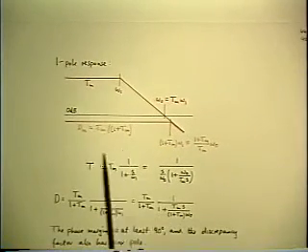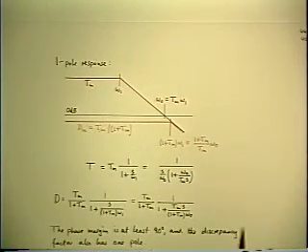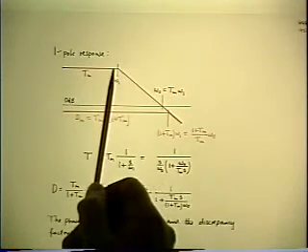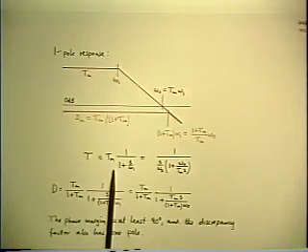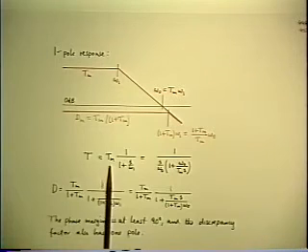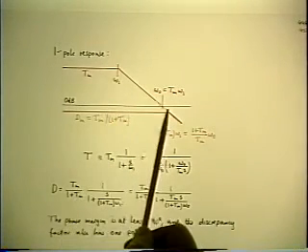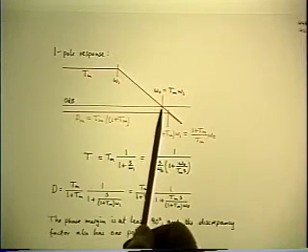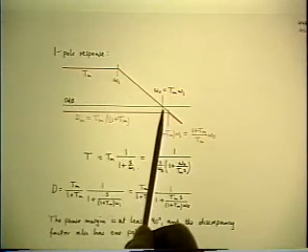We can do it graphically, which is basically what I just did, or you can set it up analytically by changing the parameter which we used to represent the original T. That is, by gain bandwidth trade-off, the crossover frequency omega 0 is equal to Tm times omega 1.